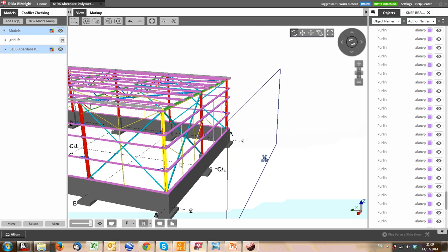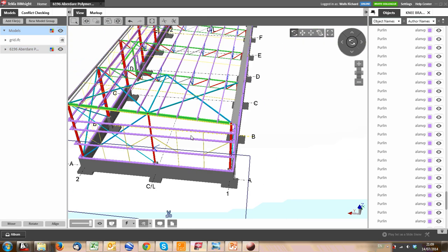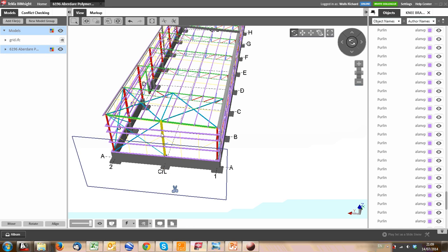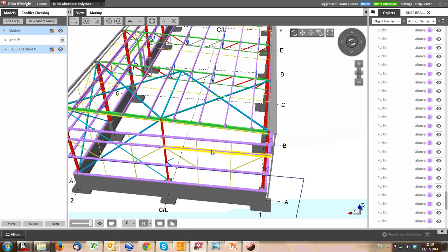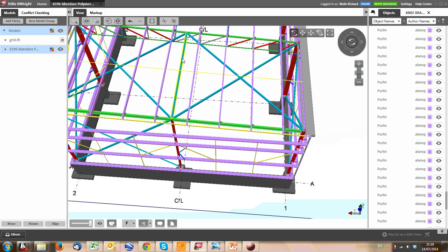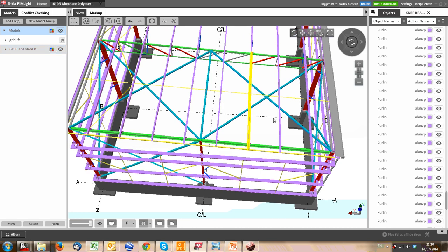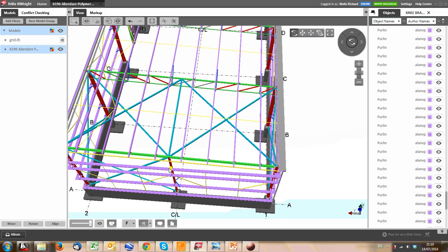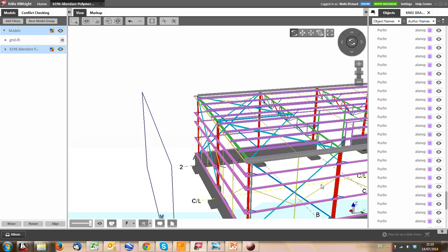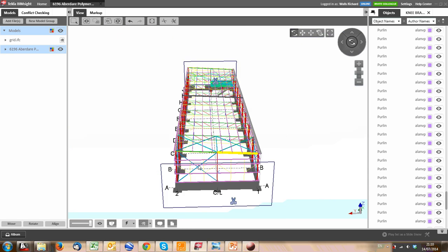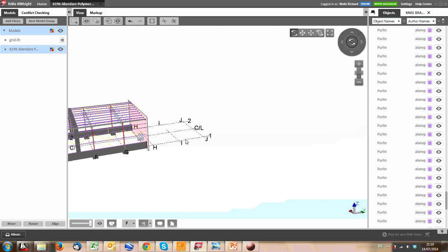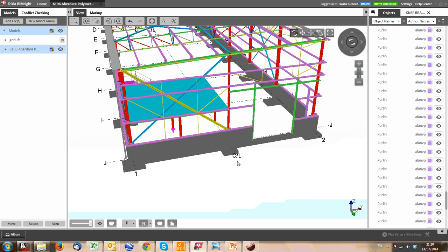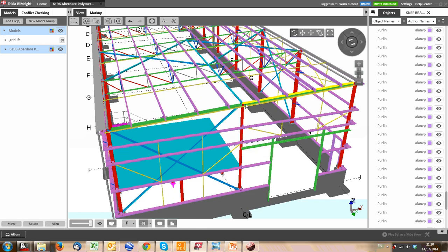And our vertical bracing on the side, vertical bracing on the other side. So if the wind blows from this side and it blows on this face, the load goes from those girts to that column, up the column to the top, and down the bottom to the concrete resistance. At the top, the load will go down this pipe, this compression member, to the tension angles, and it is braced out. So we've created a little brace structure, so at least that column is supported, and that is supported then down these braces to the side, and the same on the other side. Oops, there we go. So this load will go up this column and then down.